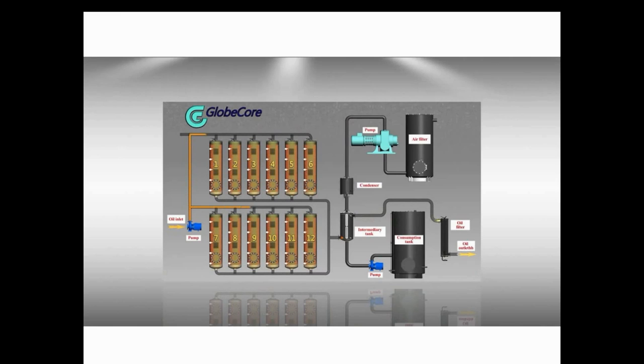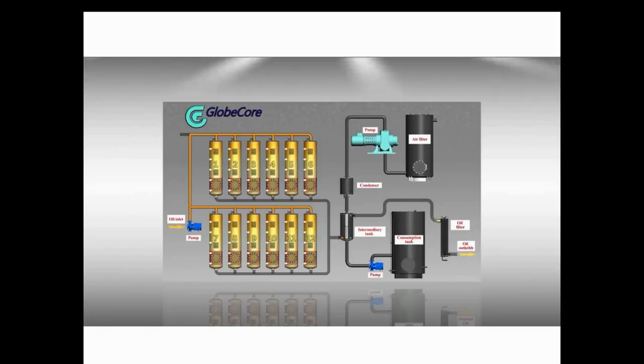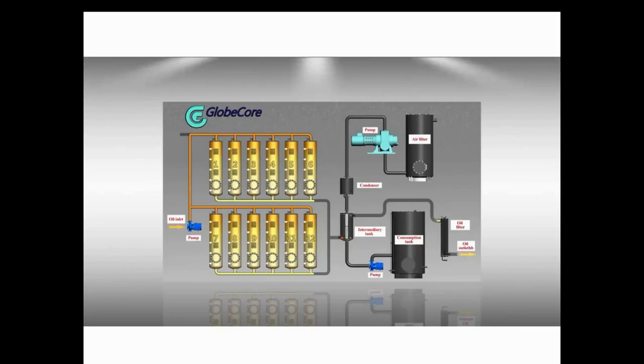Now, Fuller's Earth independently goes to reactivation, and a degasser of, let's say, 4,000 liters per hour capacity continues mixing oil in the transformer. In 16 hours, oil in the transformer is not 0.1 acidity anymore. It is 0.07.